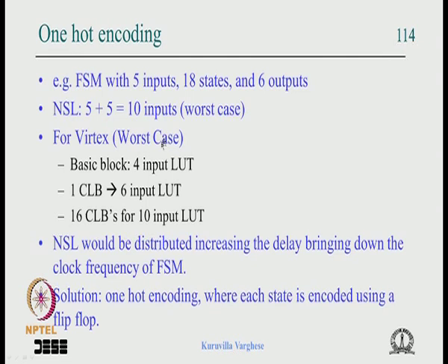While decoding a state, you don't need 5 bits representing that one state. You can take 1 bit representing that state. That is the basic idea. So each state is a flip flop.